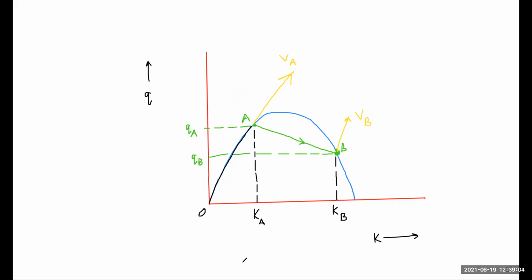So here in the diagram, the speed of vehicle at state A is given by line OA and the state of B is given by line OB. The same speed can also be shown on the same time curve of the traffic stream. All the lines having the same slope imply that they are moving with constant speed.